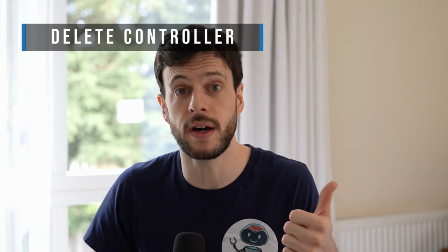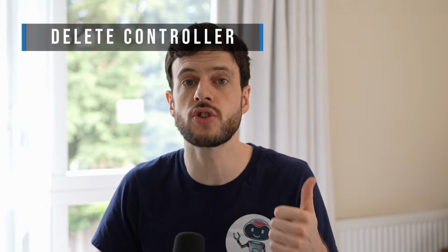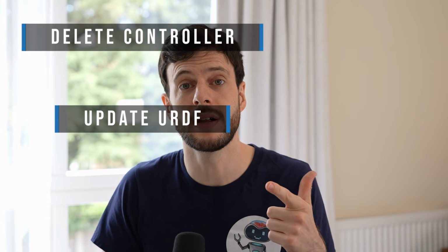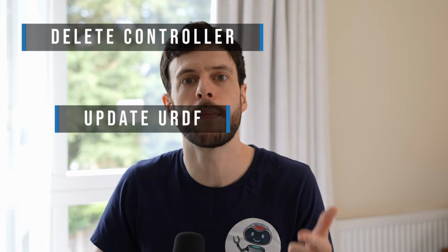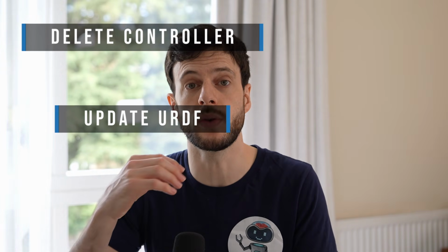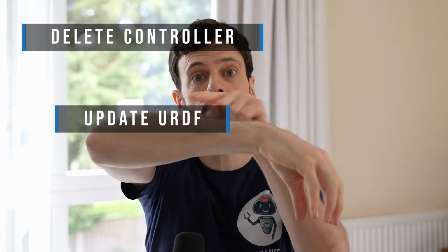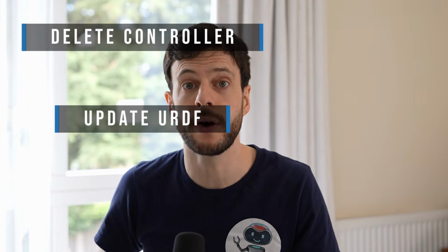The next step is to adapt this example to be used for a real robot arm, and we've seen three main changes that we need to do for that. First, the controller is the simplified version, so we don't need that, we can strip it out completely. The second is the robot description file, which we don't need for the controller, but it is useful for being able to do the kinematics, to convert a target tool pose into the joint angles needed to reach that pose.